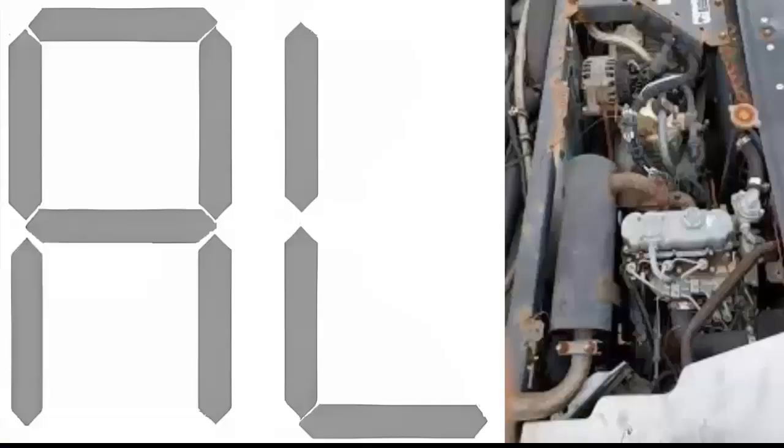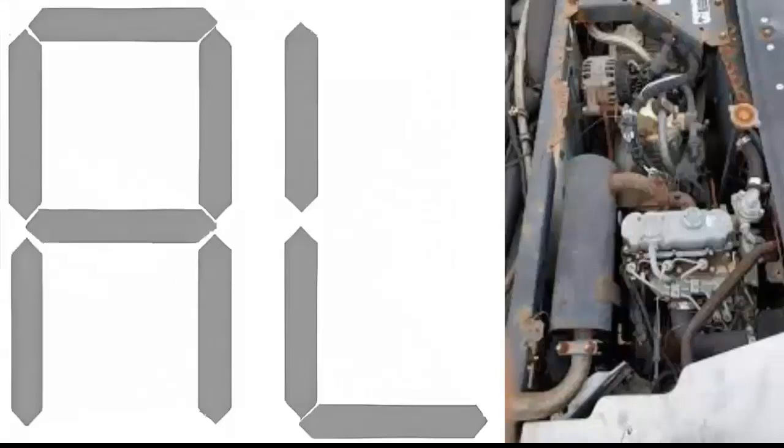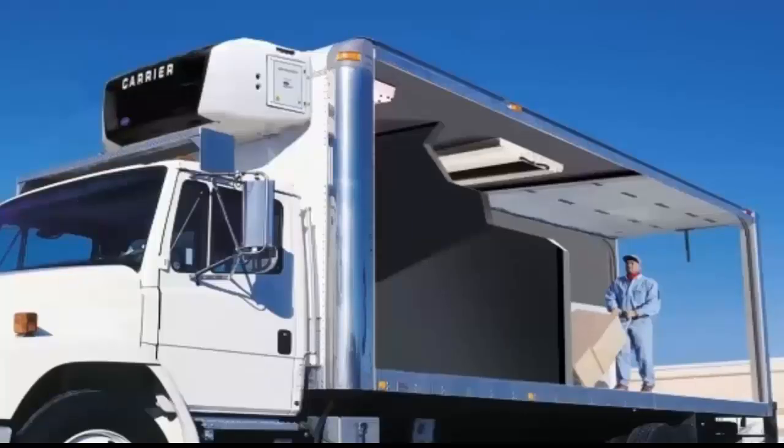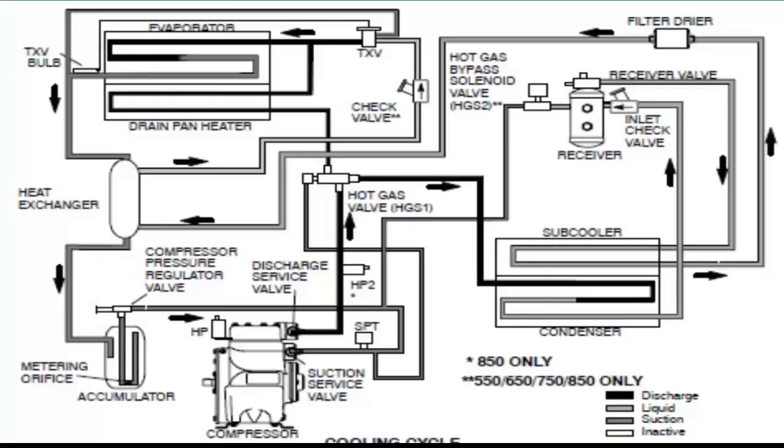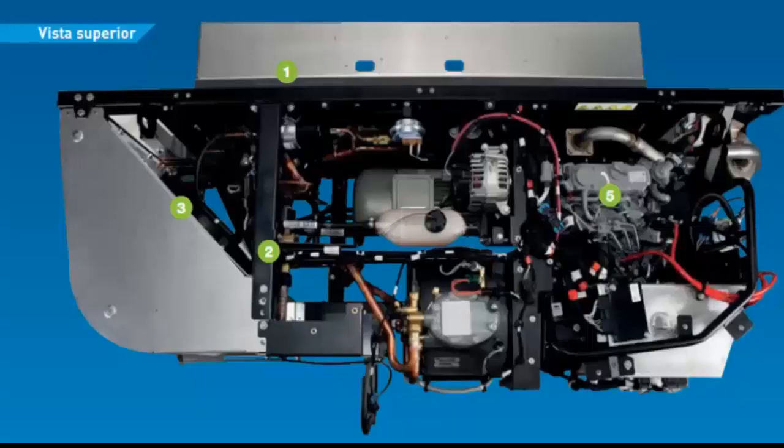7. Incomplete defrost cycle. This fault is identified with code AL6 and could indicate issues with the temperature sensor, airflow blockages in the refrigeration system, or direct failures in the defrost process. It is recommended first to inspect the sensors, airflow through the internal unit coil, and verify the defrost system.